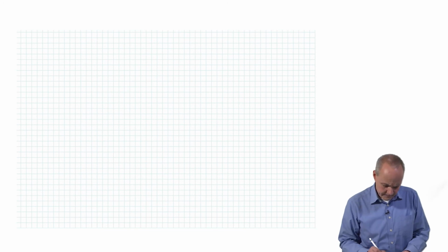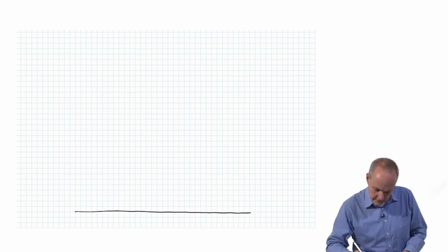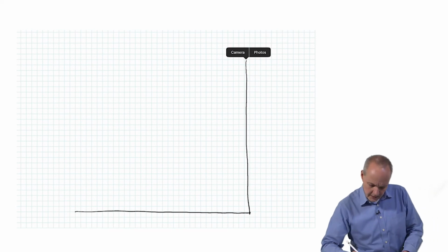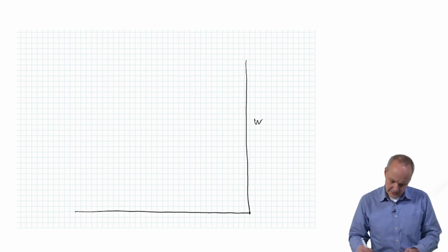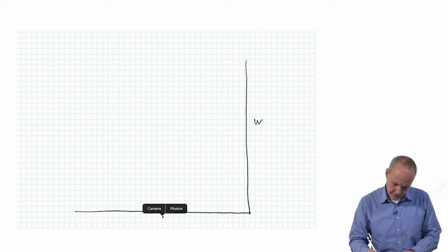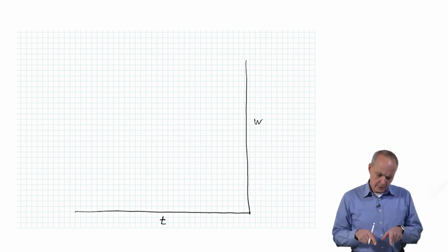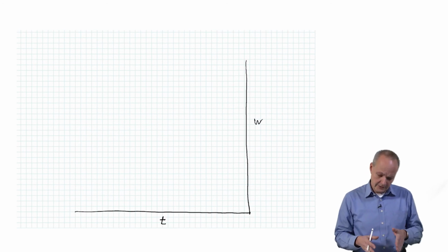Unfortunately, while these are the fundamental variables, they are not necessarily the variables which give you the perpendicular axes. If you remember our psychrometric chart, we had the humidity ratio over here, and on the horizontal axis the dry bulb temperature, right? But even though it almost looks linear, if you look very closely, this is really not a linear variable.